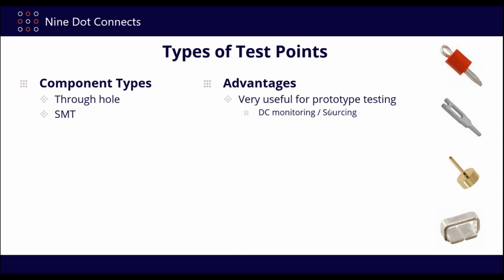There's going to be no signal integrity issues on these. I can trust you that. There'll be less stress on the probes. So if you're not having to hold it there or stick it into a hole in the board, we'll talk about that more in a moment here as a way to keep the probe onto the board. But it's less stress on the probe to use these things. And they're really great for testing and long-term debug.